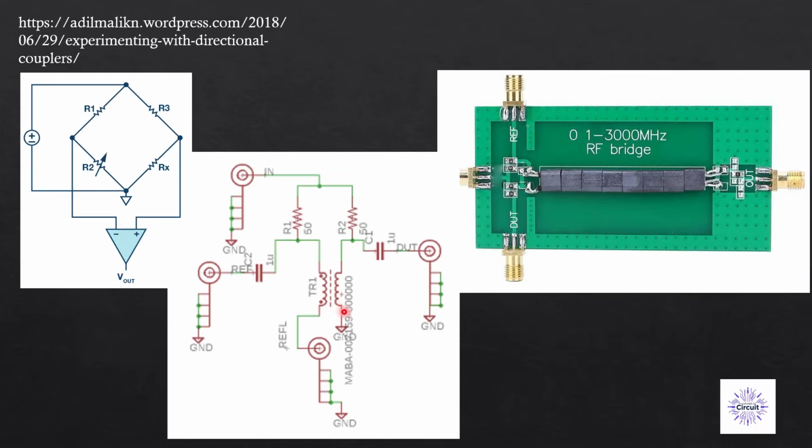One idea is we can use another type of device that is usually used in RF design. It's called a balun. A balun is essentially, by using RF transformers, a way to create a differential to single-ended conversion.